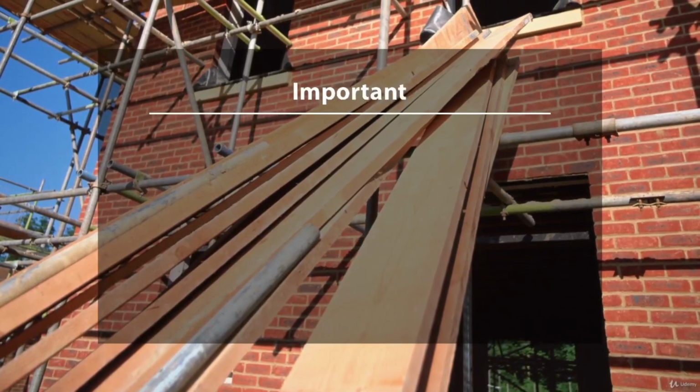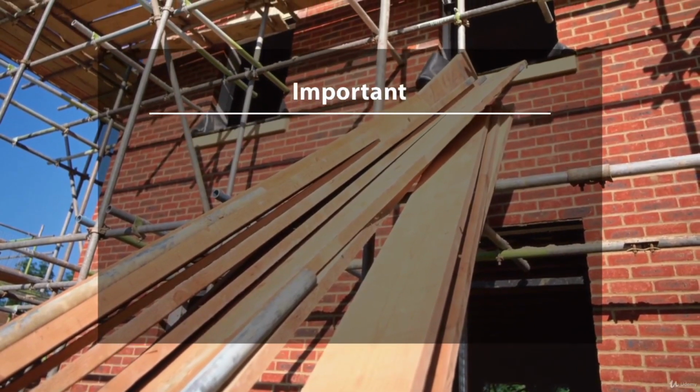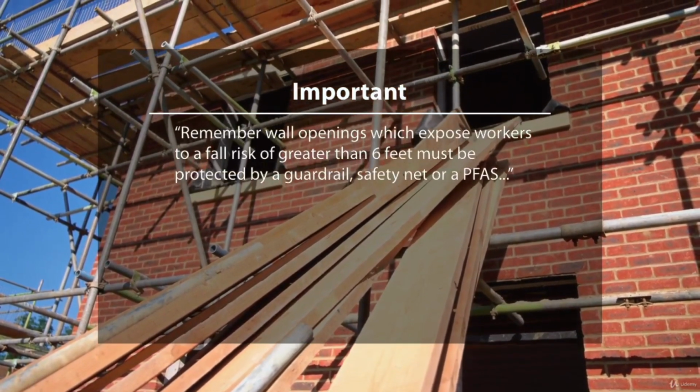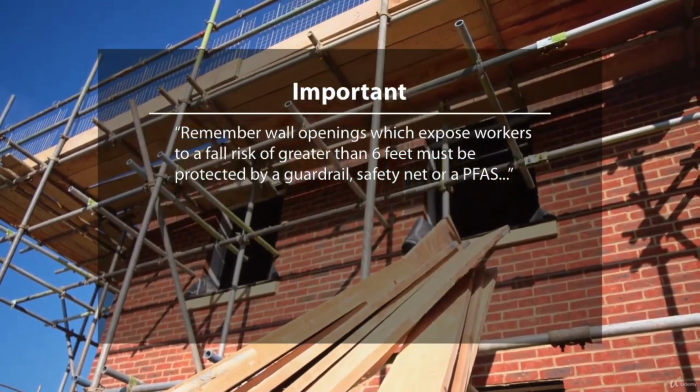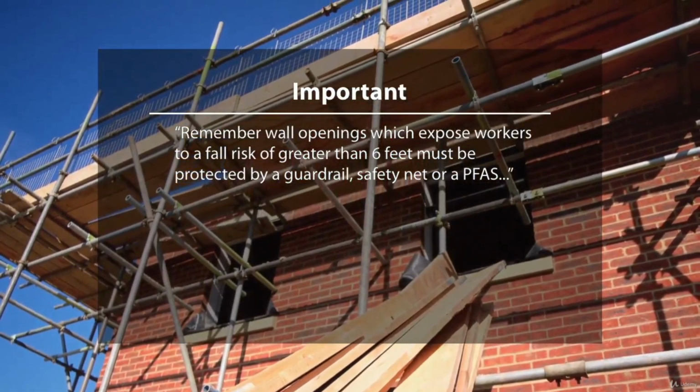Whenever employees are working on, at, above, or near wall openings, including those with chutes attached, where the outside bottom edge of the wall opening is 6 feet or more above lower levels, and the inside bottom edge of the wall opening is less than 39 inches above the walking or working surface, as in the case of a window, employees must be protected from falling by the use of either a guardrail system, a safety net system, or a PFAS.